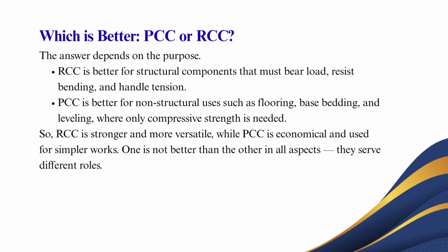Then the point comes to mind, which is better, PCC or RCC? And the answer depends on the purpose. RCC is better for structural components that must bear load, resist bending and handle tension. But the PCC is better for non-structural uses such as flooring, base bedding and leveling, where only compressive strength is needed and not tensile strength. So the RCC is stronger and more versatile, while PCC is economical and used for simpler works. One is not better than the other in all aspects. They serve different roles.